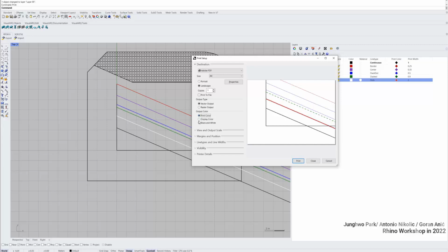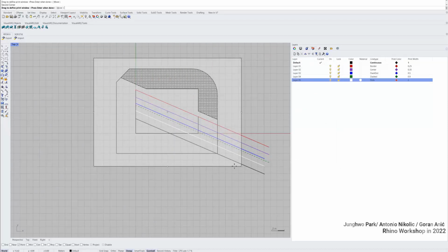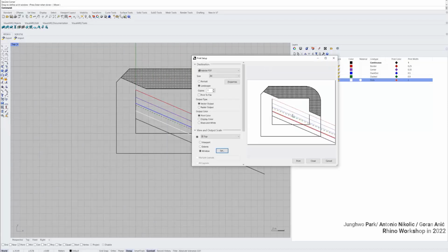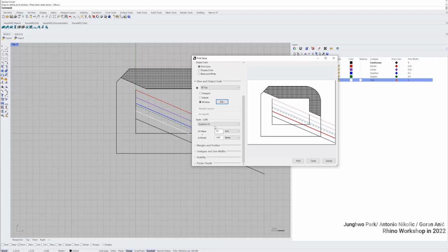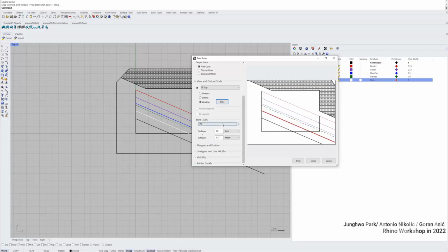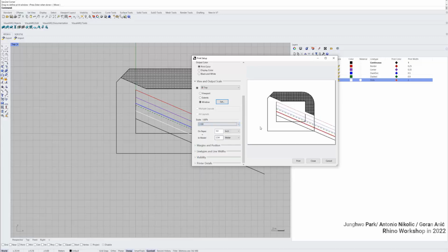Instead of using the top view here, I'll set the window from the view out scale. I'll set window, and the window I'm going to set a bit like this, and I hit enter. That's the A4 size paper that we can get with different line weight, and you can also scale it to different scales, 1 to 50 for example, or 1 to 500 in A4 format. Let's make it 1 to 100.